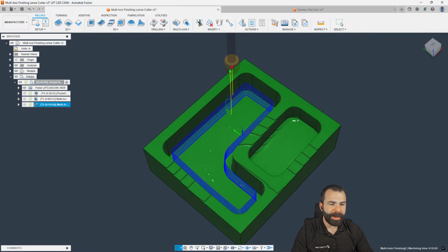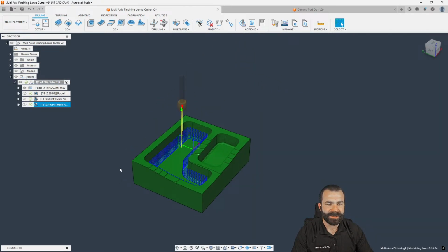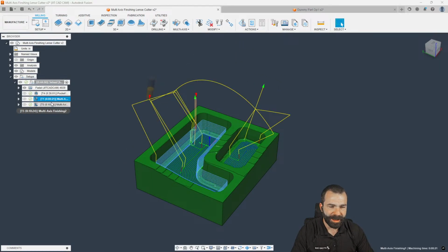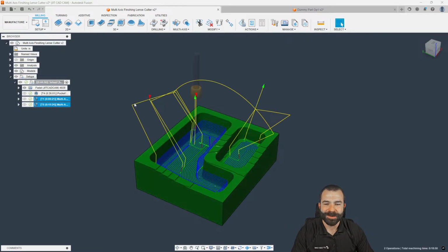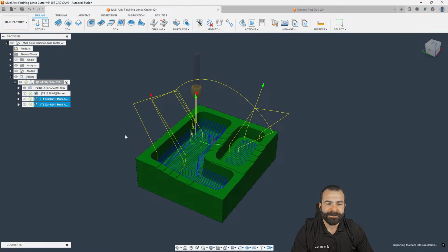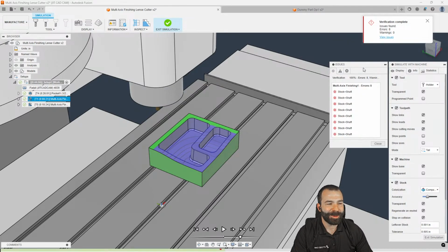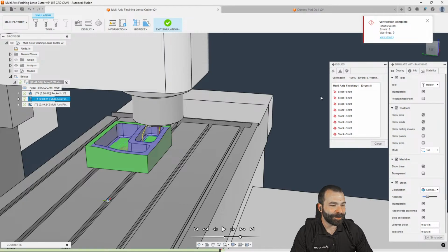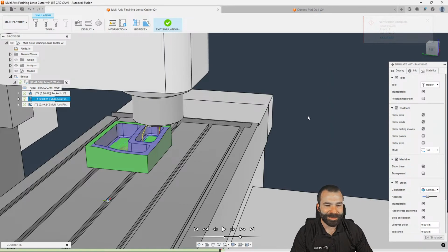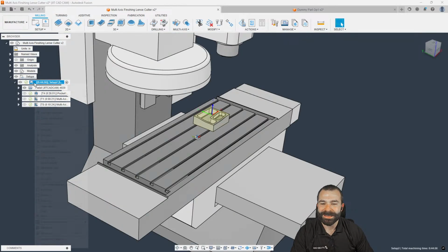So we got our toolpath. We're using our barrel cutter. Now, I am using a lot of the default settings here inside of Fusion. I will also take the blame for the fact that neither one of these tools have tool holders, so we may have to go back and change those, but let's go ahead and simulate these here. As we pull up our machine, we are probably going to get a warning, and that warning is going to tell us nothing more than, guess what? We're slamming into different areas of this part. I'm also surprised we're not getting a warning that this isn't a multi-axis machine. So with that, we may need to go back and swap out our machine.